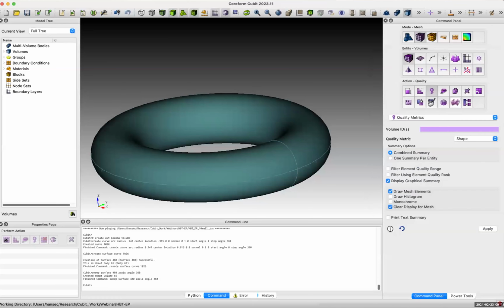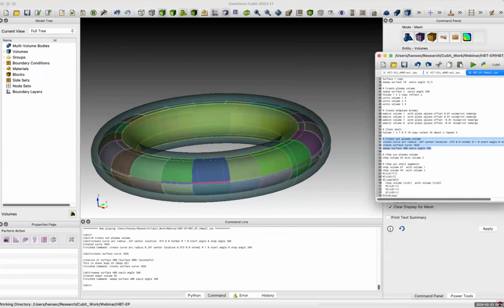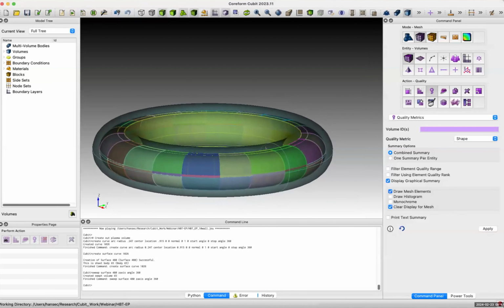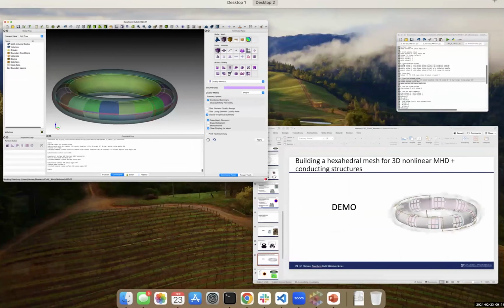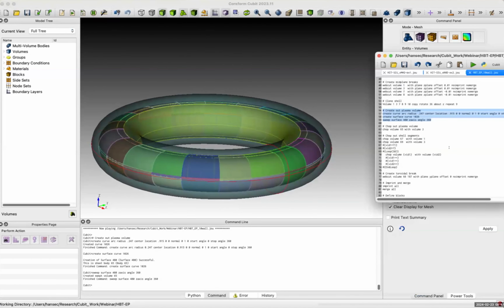All right, and now I'll make things transparent. Okay, so now I have all these regions. I need to make the geometry compatible going forward with Cubit. Basically, I need to make cuts in this larger volume of all of the other components so that then I can imprint and make sure that all the geometries match. So I'm going to do these through chops.